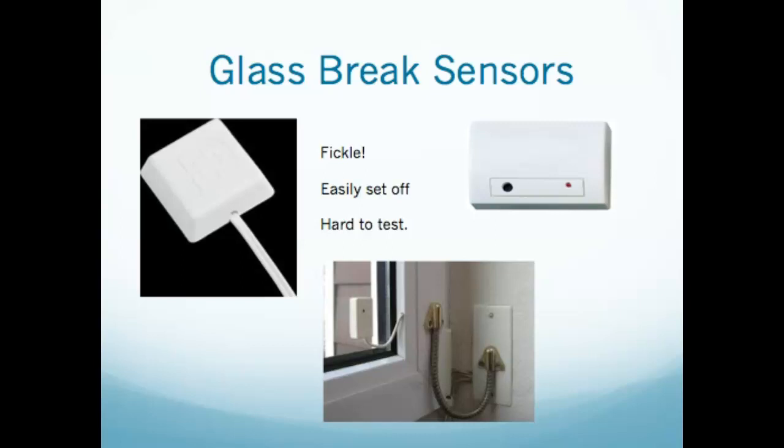They really do need to be properly tuned and in the right environment. These, on the other hand, are much less likely to give you false alarms or nuisance alarms, and we'll distinguish between the two in a minute, but they're harder to test. How do you know? What you test these with is a stick, essentially. You're shaking the thing a little bit, and then you have a tuning fork that's tuned to the sound of breaking glass. It's really old school.